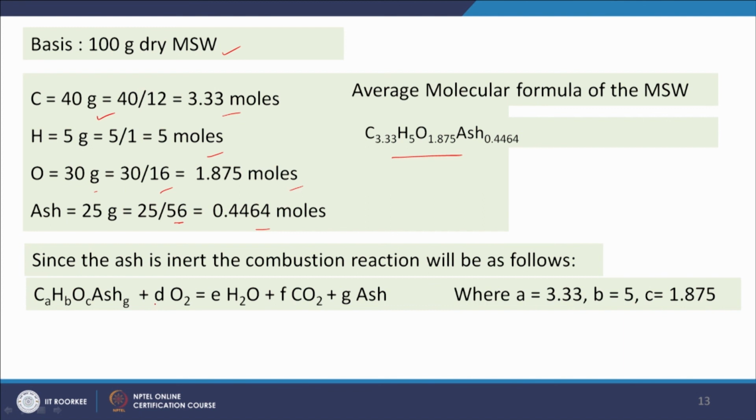So, by doing some balances of elemental mass, that is carbon balance from both sides, hydrogen balance, oxygen balance, ash balance, etc. So, we will get some relationship with this E and these known variables, and from that relationship we will get the value of all these unknown variables, and once we will be able to find out the value of D, that the stoichiometric requirement of oxygen we will be able to calculate, and since 4:1 is the ratio of nitrogen to oxygen in the air, from that we will also be able to know the air requirement stoichiometrically.